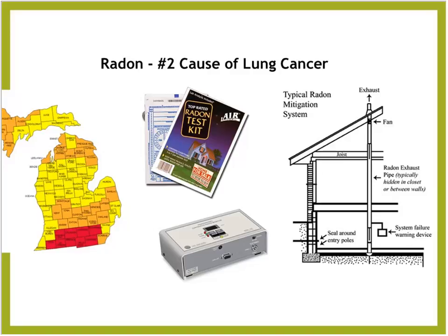If you're building new, even if you're in the least rated zone, we highly recommend that you just put the system in. There are devices coming out that can actually monitor radon. How well they work, we're not sure, but you can put the fan in and you can make it a passive radon system with an active fan in there. And if the monitors go off at some point or they keep retesting and find an issue, it can always be activated later.